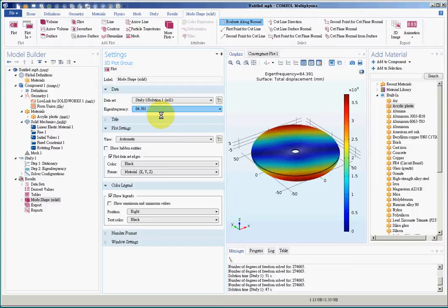As we said before, the external force does not affect the natural frequency of a structure. But how? Again, here the rotating speed generates an external force, right? But the external force actually increases the internal stress of the structure, and the internal stress will increase the rigidity or stiffness of the structure, and thereby increase the natural frequency of the system.